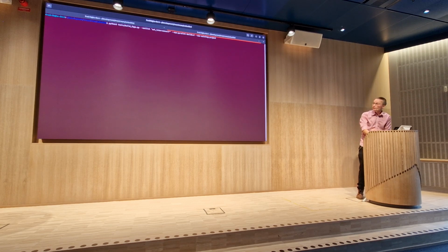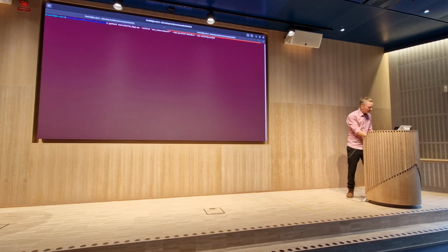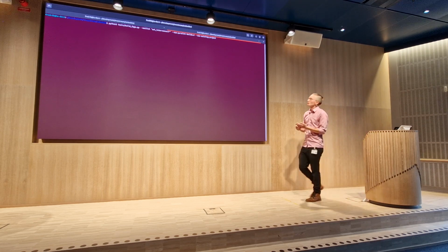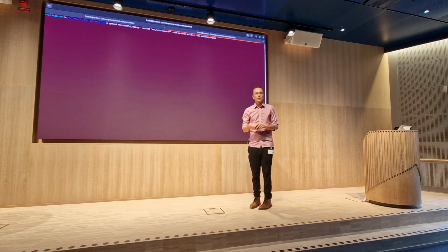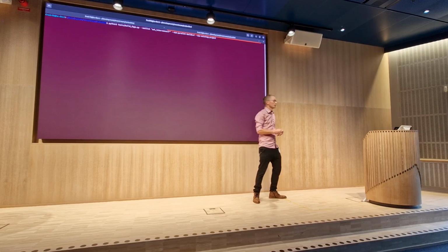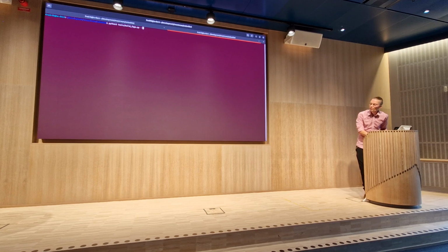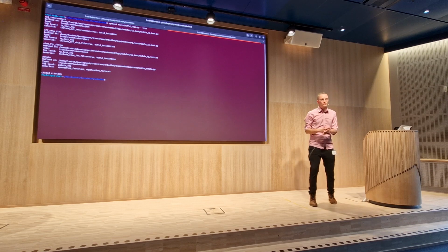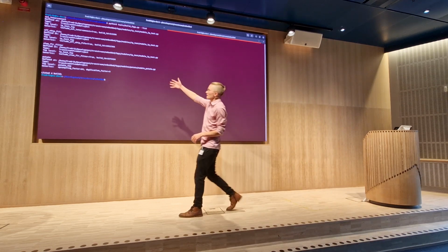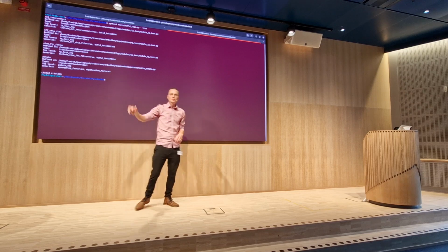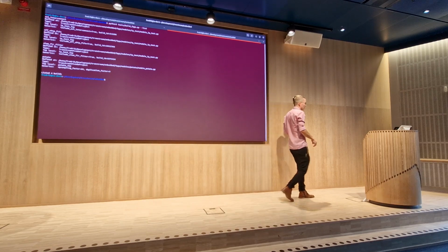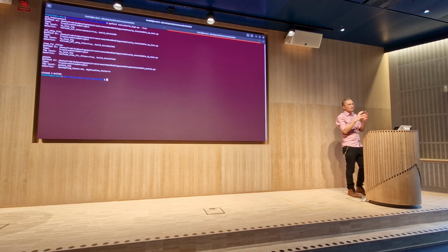So, with TSFPGA, we have one entry point again for the builds, just as with simulation. So in this script, I wish I had this on my small screen as well. That just lists all builds that are available. Very similar to VUnit, right? So here we have just 4 builds, but these are our top level builds. In this case, we want to run our netlist builds. We just build submodules and check the sizes of these.